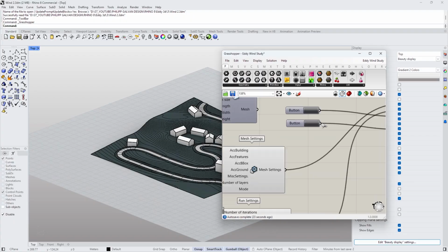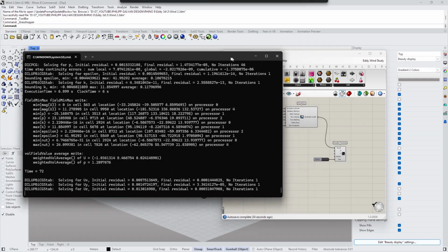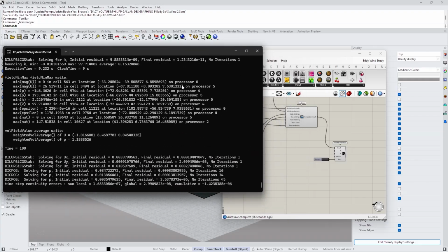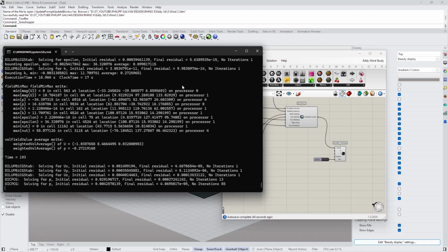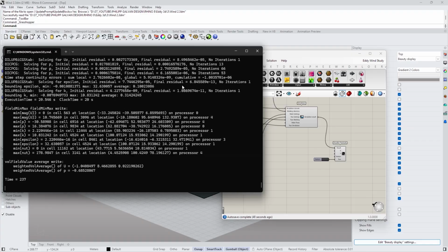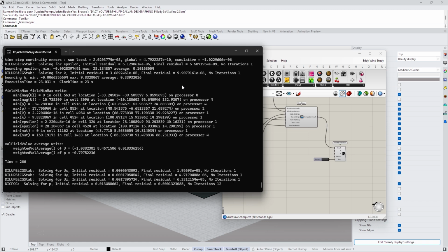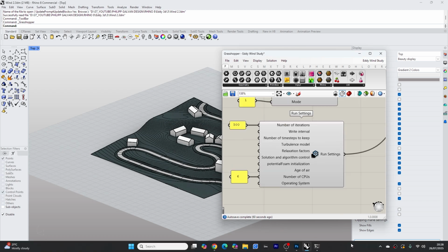Okay, that's good. Quick note, if your simulation crashes, then most of the time it is not this software's fault, it's yours, and you have to just go through, check everything, and come back and try it again. And now we can run a simulation. That looks good. If it doesn't stop right away, it means it runs through all the iterations. If it stops just right in front, it means something went wrong and it stopped. So basically it runs now through this 500 times.